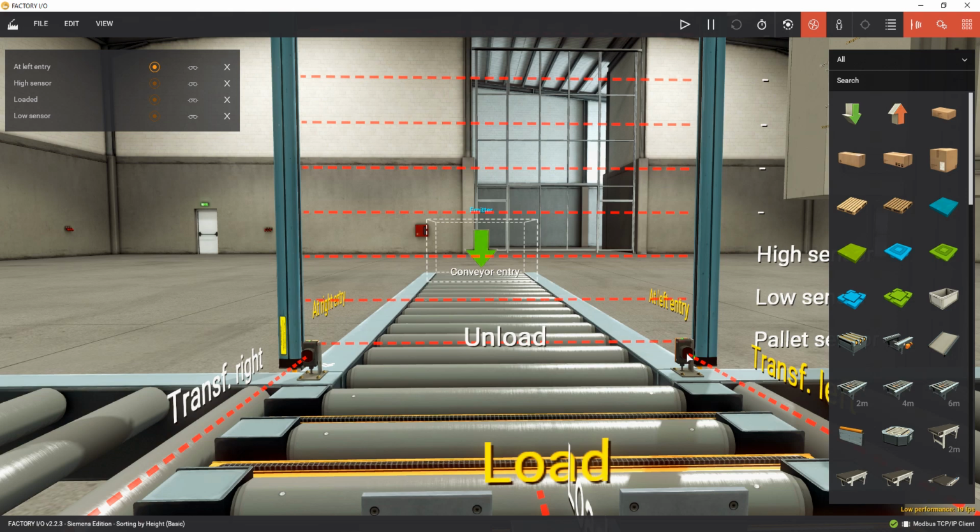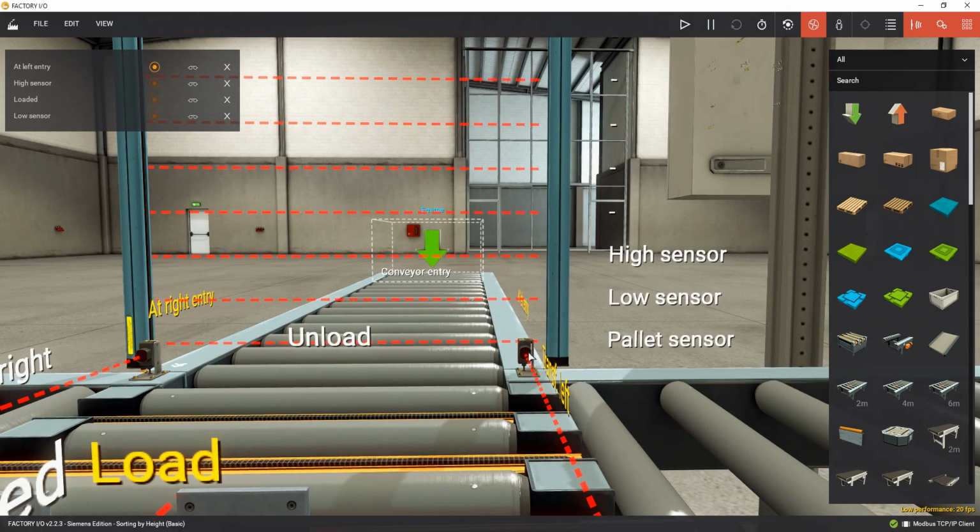You can do it in your own spare time, but what I can just tell you is that you need a timer to count for approximately 10 seconds because I've done my homework. We'll make it 8 for argument's sake, then the transfer chain will stop and the conveyor belt this side must start running. So why are we doing it like that? So that we don't have stuff colliding. So we are sure that the box would have passed, or the pallet would have passed this sensor here by the time the timer stops running.